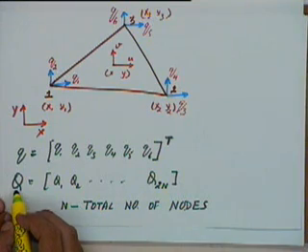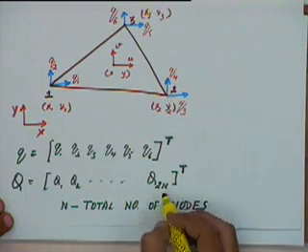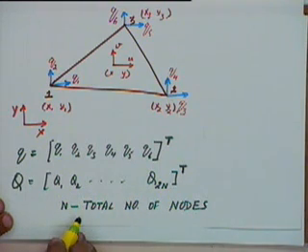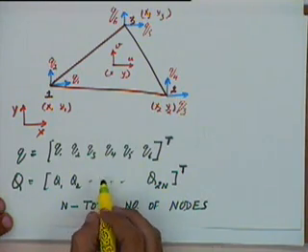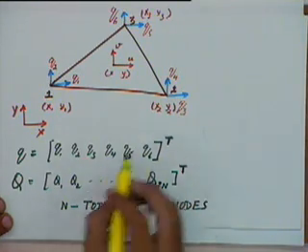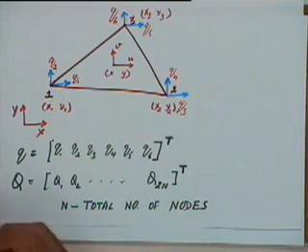Okay, and the global deformation vector will be given by this vector. Okay, it will have 2n elements if n is the number of nodes. So therefore individual location of that won't correspond to a particular node, that will only correspond to deformation in one direction of that node. Okay, and each individual location will normally be referred to by the term degree of freedom.